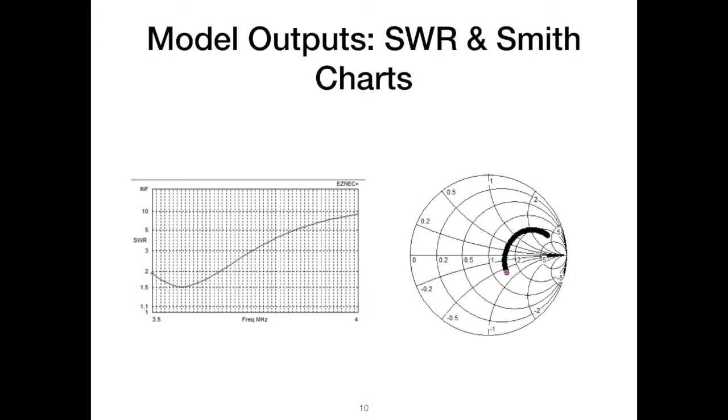And that was another reason why we want to put an antenna tuner on that, so we can keep it within a reasonable range and not let the standing wave ratio get too high. Is that saying the elements were probably too short then to go to the center? Too long. Or too long? Too long? Too short? Too long?